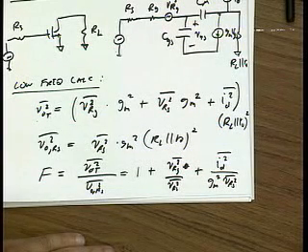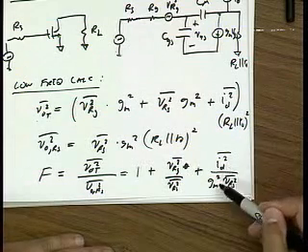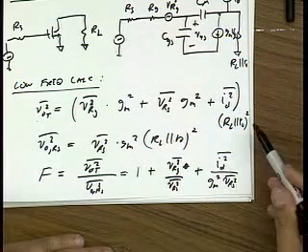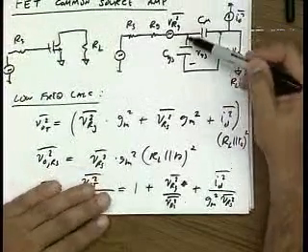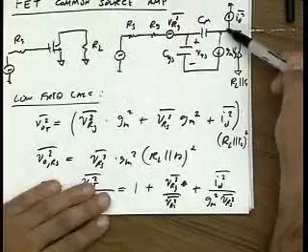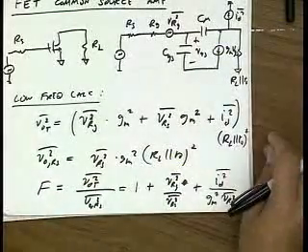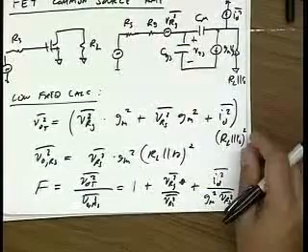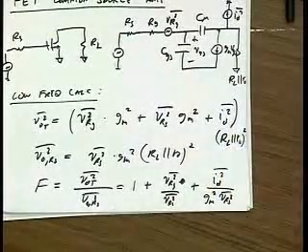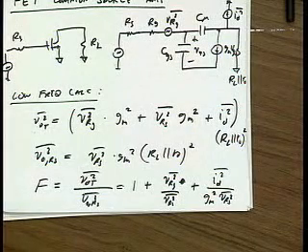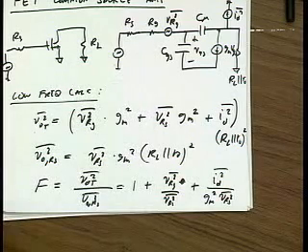Okay? So if you look at this carefully, you can see that this term looks like an input referred voltage. If I had just added another voltage source in series to account for ID, it would have been an even simpler calculation. But this is simple enough. Does everybody understand this calculation? Any questions? Because this is as simple as it gets.